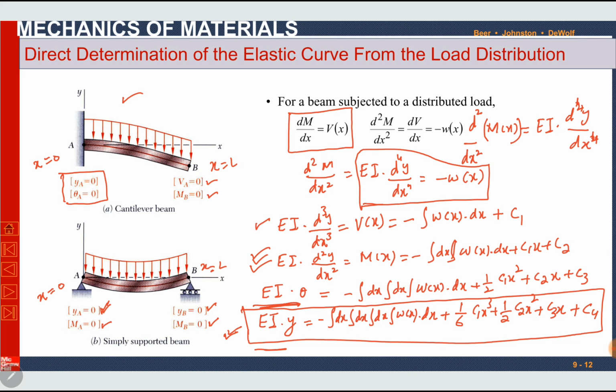At all the pin supports and roller supports, there is no moment, remember it, but there is a reaction force, so the shear force will not be equal to 0. Similarly, at free ends like this, where there is no concentrated force, there will be no shear force, and even there will be no bending moment. At all fixed supports, there will be no deflection and no slope. At all pin supports and roller supports, there will be no deflection and no moment.